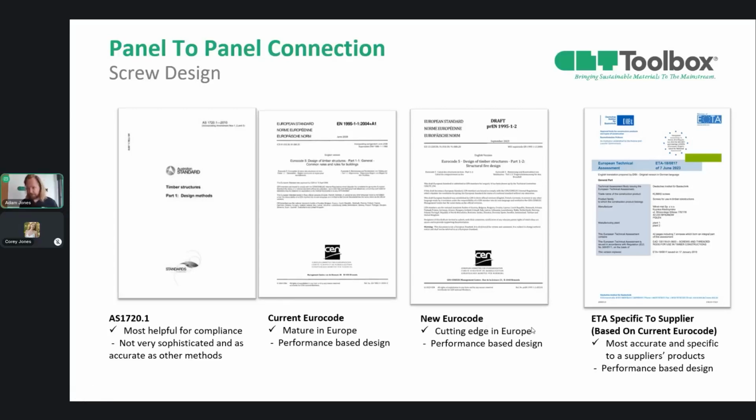Having said that, there are some other parts around the world where I hear things on screw design, things coming out of Canada and so on. And then finally, you've got the ETA specific to suppliers. So don't be mistaken, that's not just a simple solve it once, use it once, checked by us. We do that with each individual supplier. We go through about an 8-week, or 8 to 12-week, process where a structural engineer and software developer produce a calculator specific to that supplier.